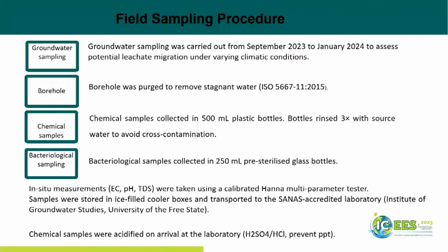In this study, which was done with one of my students whom I assisted, we did sampling for 6 months. Groundwater was sampled for a period from September 2023 to January 2024. We sampled boreholes, as I said, using the purge method, with respect to the ISO method. We sampled for physiochemical parameters and bacterial parameters.